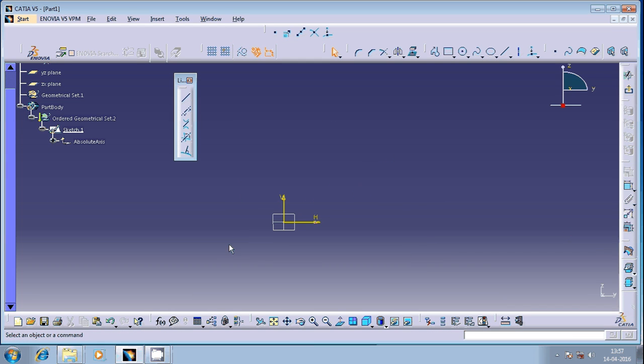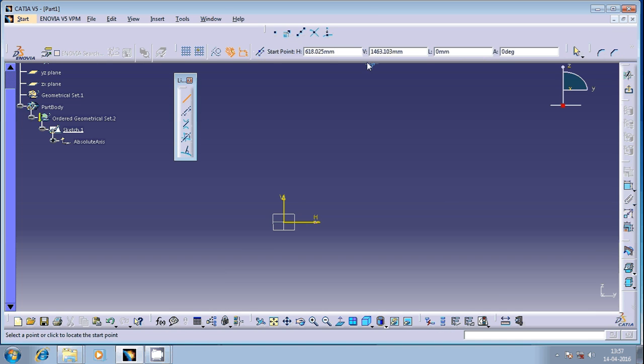Okay, there is another option. Without defining the coordinates for the second point, I can define the length as well as the inclination angle. You can see here, define the first point. It need not be 100 by 100, you can define anything. So press the tab button. It is asking for the second one. Don't select the coordinates. Straight away select the length of the line.